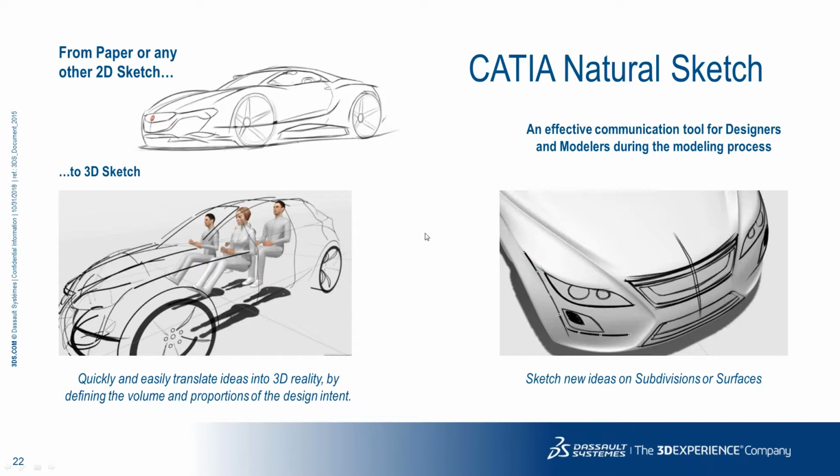And then even as the themes mature, or if you have a scan, you can sketch directly on top of those objects with raster or vector-based curves. So you can see, kind of looks like a pencil drawing across the grill treatment. And then if you take a look at the left portion of that fender, you can see the points. That is a vector-based curve. So it'll do either of them.